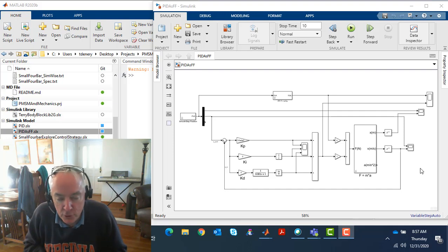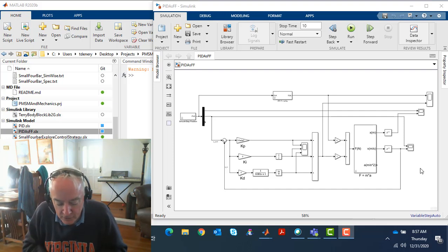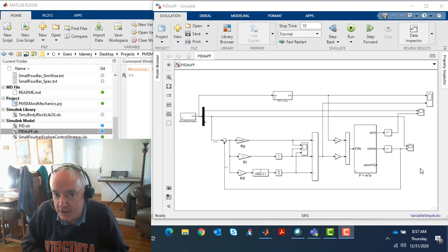They're beautiful in their ability to adapt to what I'll call the impossible request, like responding to a step function. And we're very good at judging how reasonable that response is. We also have the means, by adjusting KP, KI, KD, to tune it to be as reasonable as we can get it to be.